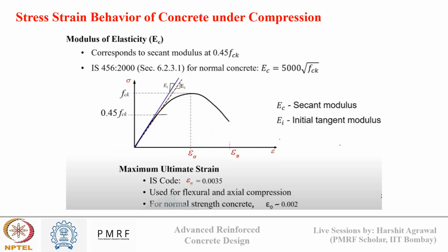Okay, now let us see each of these components separately. First, when concrete is subjected to compression, as we saw a couple of sessions ago, there is a linear increase in stress with increasing strain, then it slows down until ultimate load, and then there is a decrease in stress with increasing strain until there is rupture. This is the typical behavior of plain concrete.